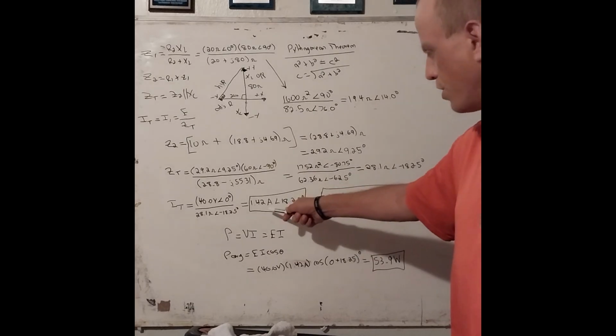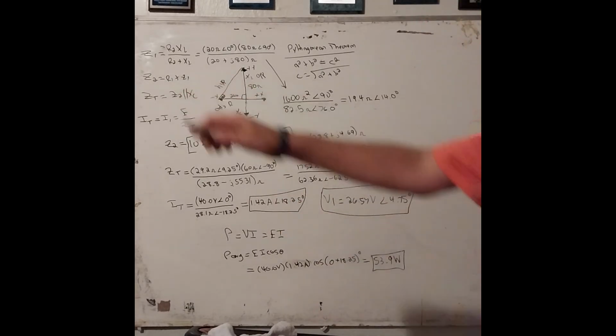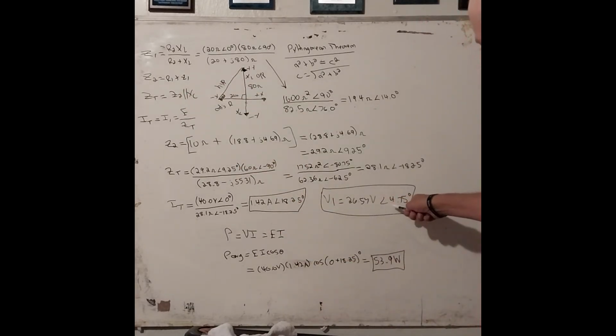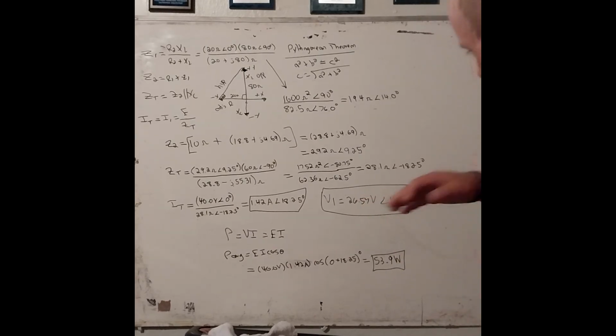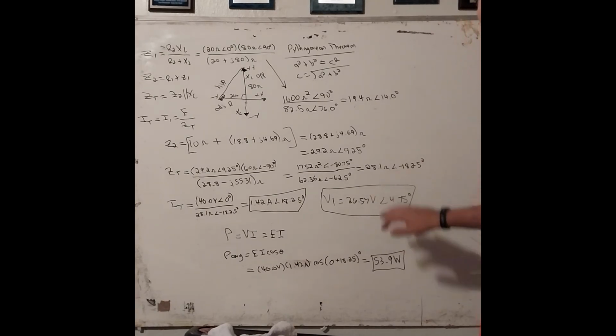This is the total current flowing through the circuit. And across the inductor, this is how much voltage and how much phase change it is compared to that. What this represents is that the angle is really closer to 0 than it is to 90 degrees, which means most of the power is being drawn from the resistive load, well, from the resistors. So I can't say much about how the capacitive and inductive loads are interacting here because I don't know the specifics of that.